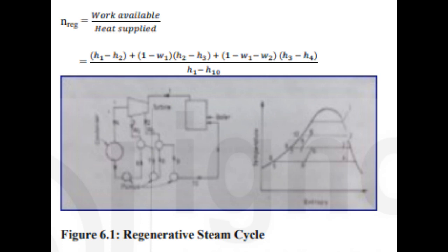It would be found that for each additional heater in the cycle, the efficiency increases. However, after the first heater, the increase through each additional heater successively diminishes until the gain reduces to a point where the capital cost of the additional heater and pump would not be justified.